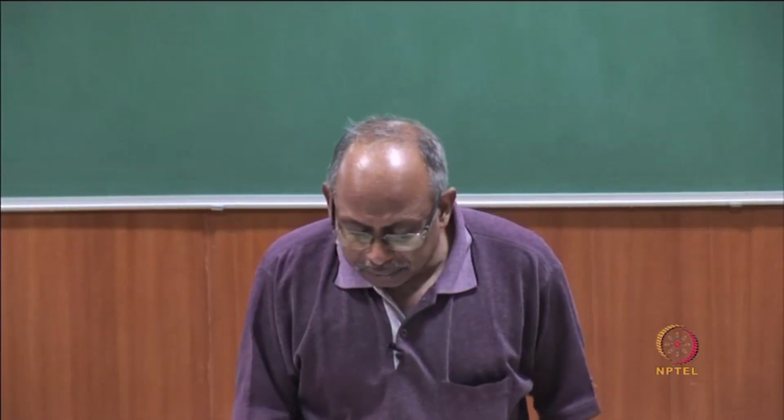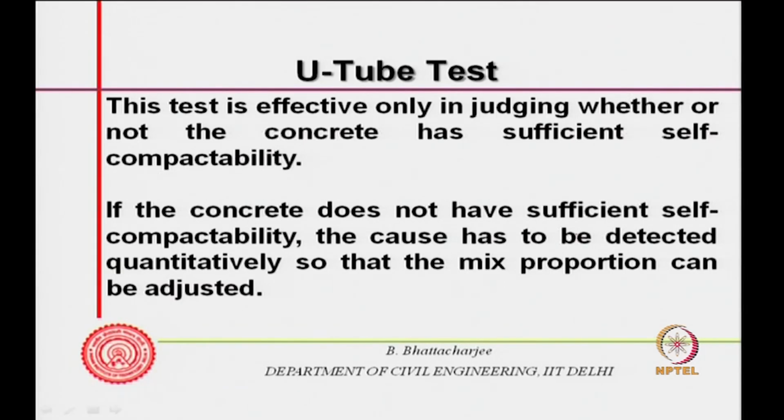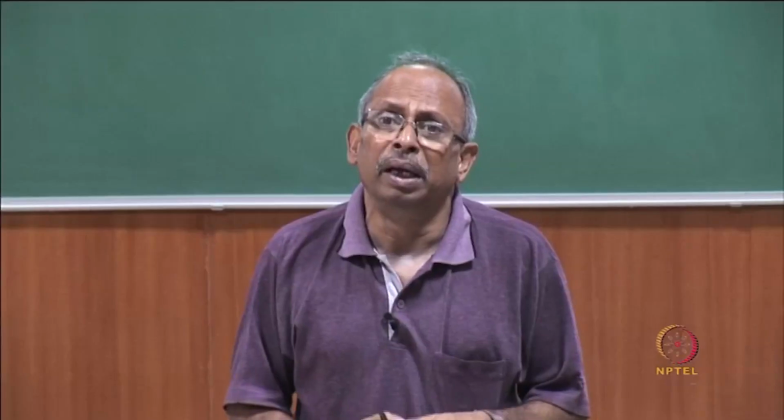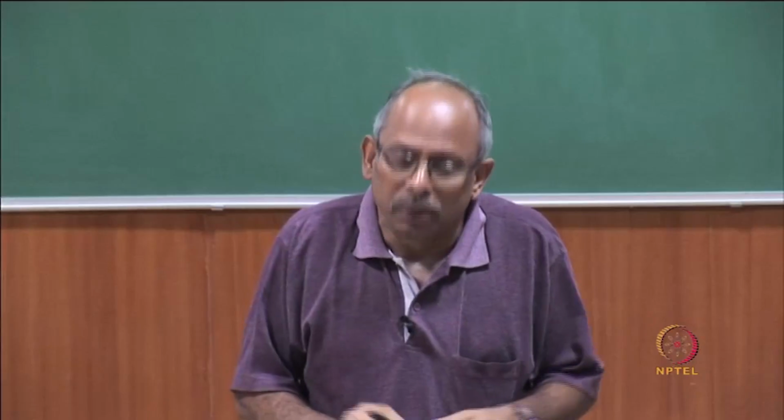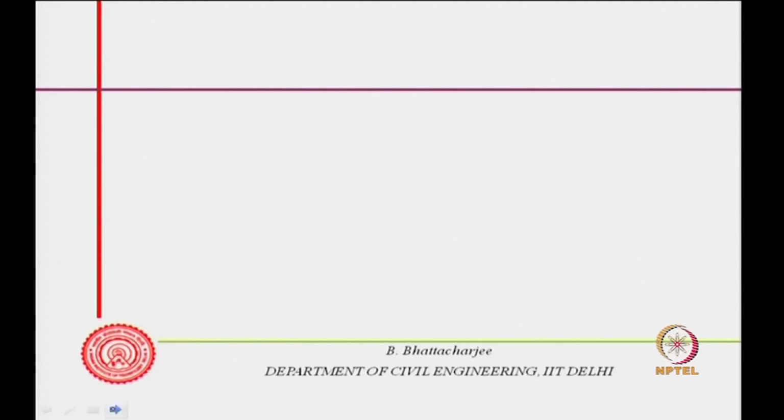If the concrete does not have sufficient self compactability, we have to detect the cause, of course, and the mix proportion has to be adjusted. There should not be any void in the system, it should compact on its own. So, this looks for self compactability.